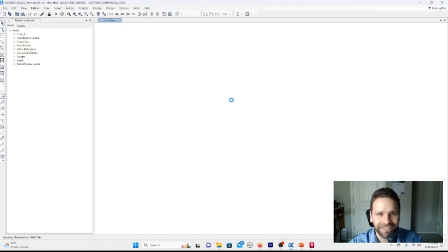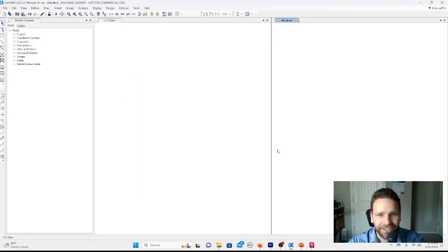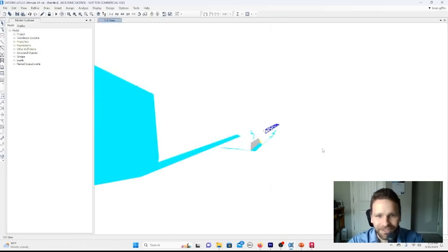It'll take a second as things load up, and then you'll be prompted to import whatever layers you have defined in your AutoCAD model into your SAP2000 model as different structural elements or members. In the case of this model, we'll treat everything as frames or one-dimensional elements, and we can select all of the layers for which we've basically defined our model in AutoCAD. So layers 1 through 3. Clicking OK. Now we basically have our model geometry imported into SAP2000.